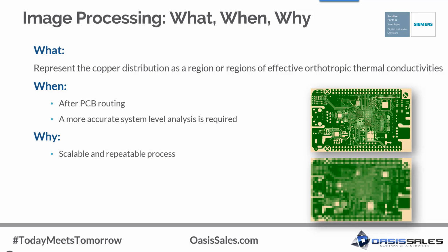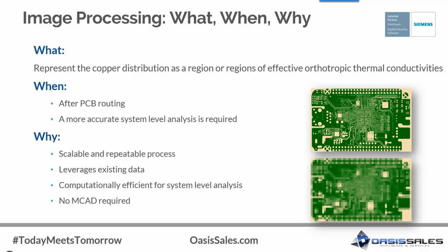Why would you use image processing? Well, it is a scalable and repeatable process, and it leverages existing data, and it's computationally efficient. It's efficient in terms of the required mesh, and as such would be suitable for larger system-level models. And no MCAD is required, as it is based on images and not MCAD models. There are 2 approaches in Flotherm for processing images.